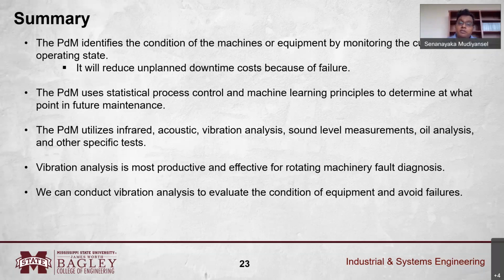PDM utilizes infrared, acoustic, vibration signals or sound level measurements, oil analysis, or other specific tests to find out when it is going to fail, or to understand where we need maintenance.